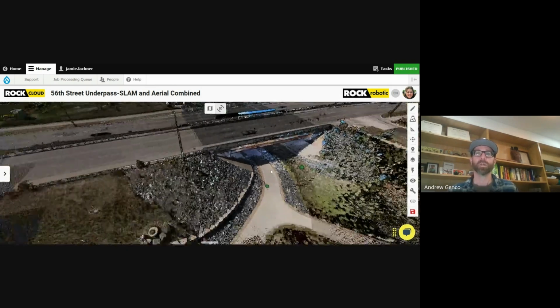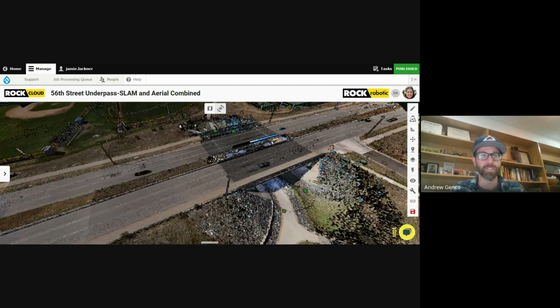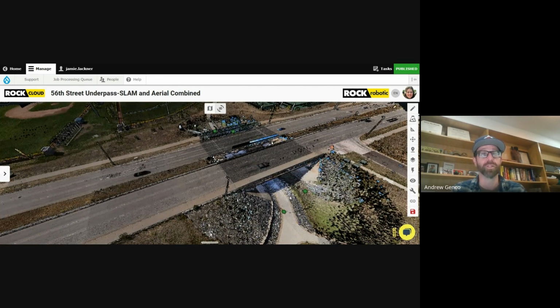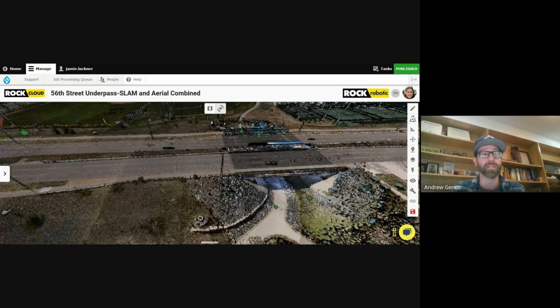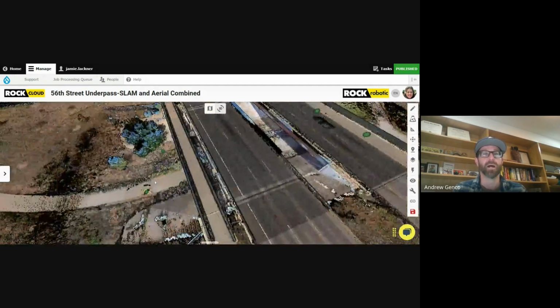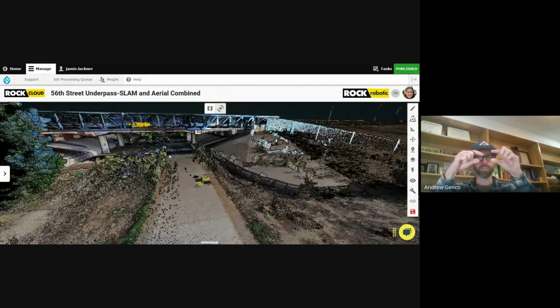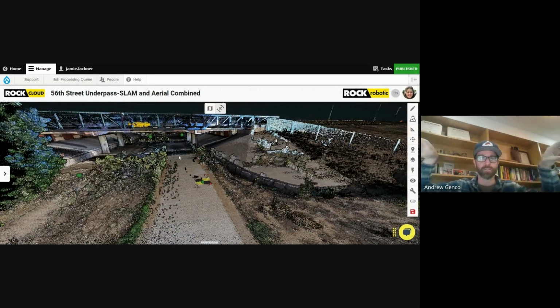So right now, some details for this area. As I mentioned, the SLAM data capture took roughly 5 minutes. However, I incorporated some testing on this site because with an underpass, there is a painting method that needs to be done. The scan for the SLAM is going out from the unit. If you can imagine it spinning like this, the lasers are shooting out that way. So for the areas of the underpass directly on top of it, you're not going to see that. So you have to do a bit of a painting method.